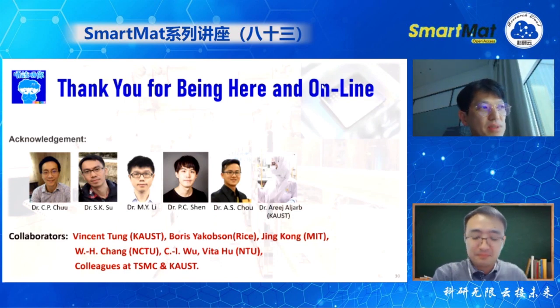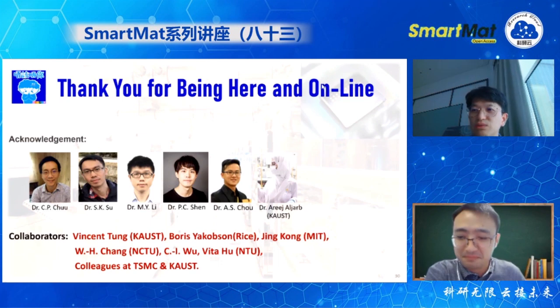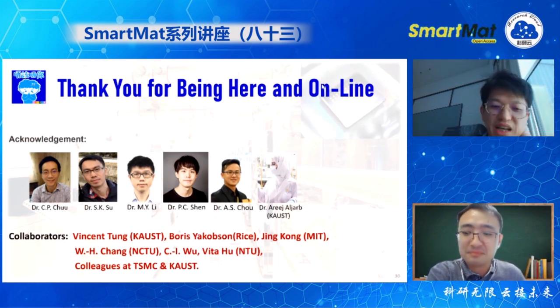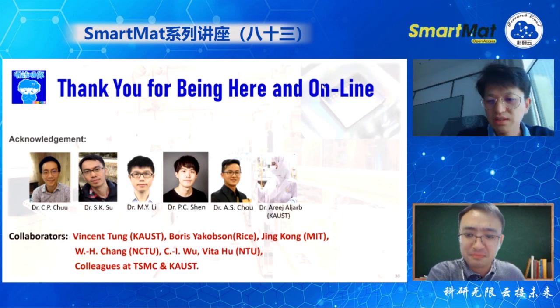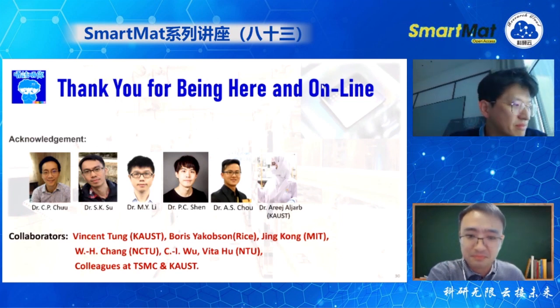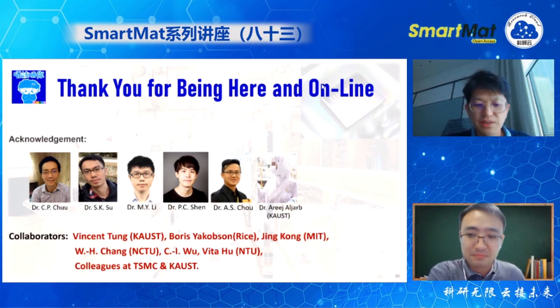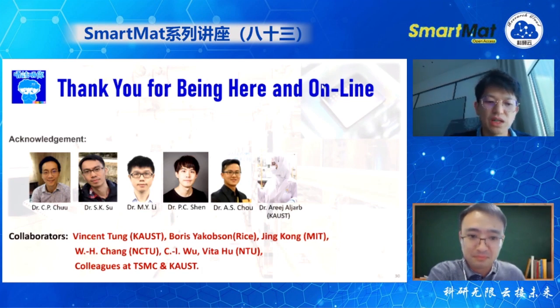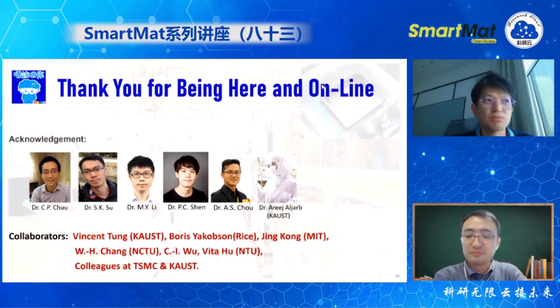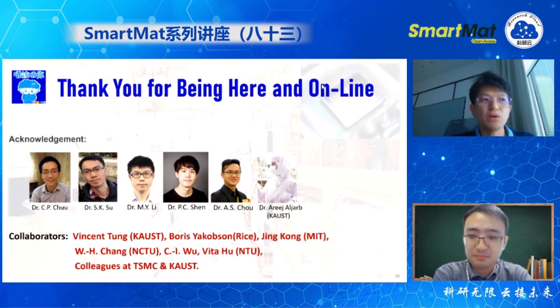Okay, yeah, thank you for your question. Again, I probably cannot represent the company to brief any ideas, but in my personal opinion, and from what I learned in academia and industry, there are many different materials which can be used for future electronics. 2D material is only one option. As I mentioned before, the thickness is about 1 nanometer. So definitely for N1 or below technology, you need to use a very thin channel. Very thin channel, naturally you think about 2D materials and also 1D carbon nanotubes.